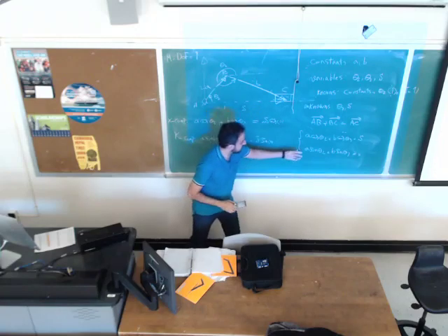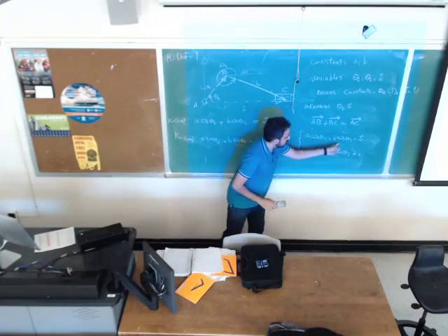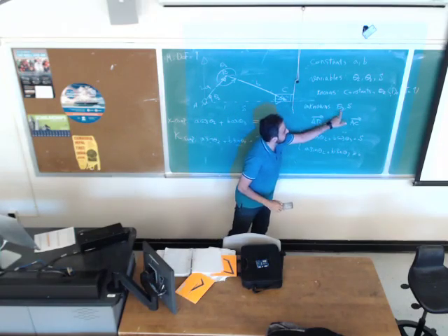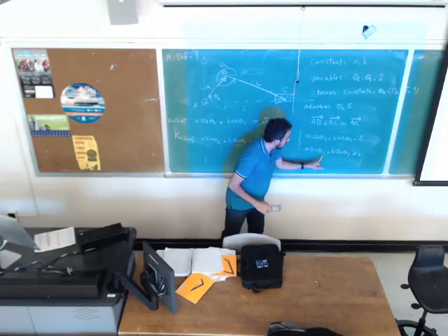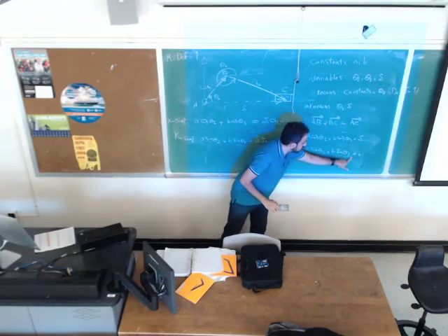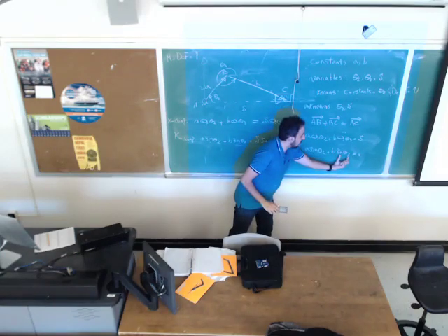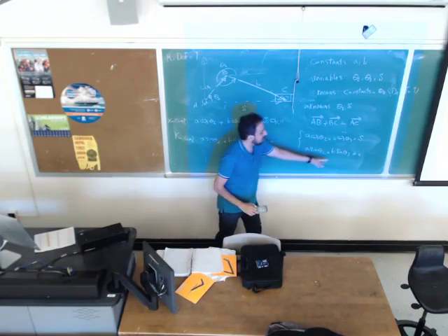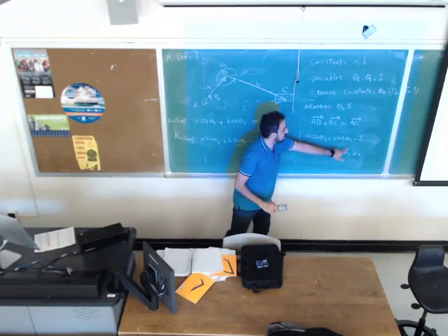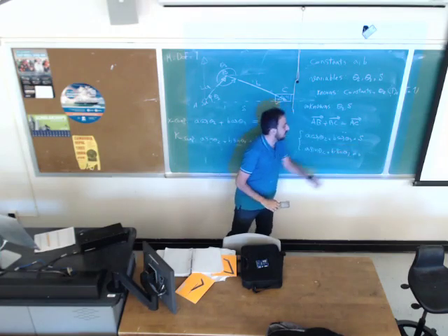If you look at this, two equations, two unknowns. Unknowns would be theta 3 and s. In equation 2, we don't have any s. So you might say that I can solve for theta 3, and after I find theta 3, I plug in here and find the s.